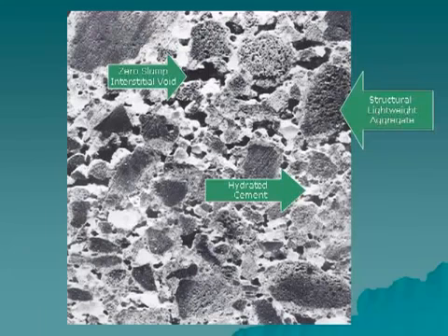This slide is a magnification of ESCS lightweight concrete as used in a lightweight block. Since concrete used to manufacture block does not contain enough mixed water to make flowable concrete as used in ready-mix concrete, the mix is comparatively dry and moldable as used in today's block-making machines. Zero-slump block concrete of all densities contain voids unfilled by cement mortar, as well as a certain amount of unhydrated cement. That is why emphasis is placed on using a well-graded blend of aggregates to help reduce excessive interstitial voids.